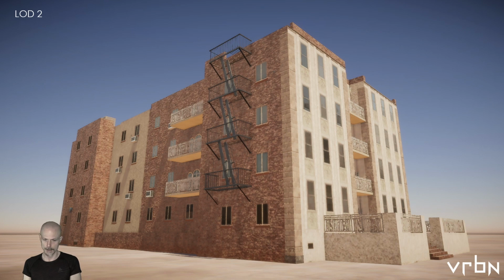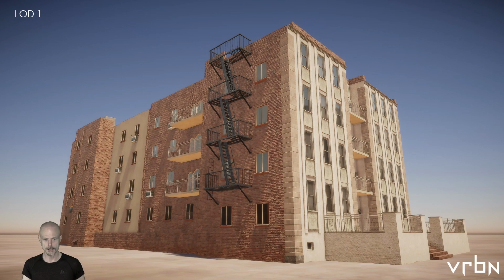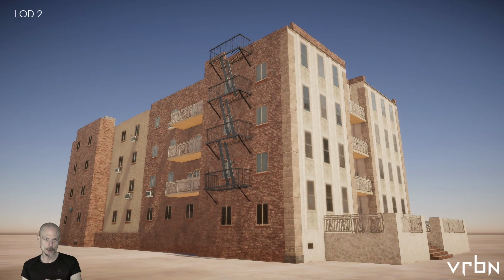And then another aspect I mentioned also before is the so-called draw call optimization for game engines. That's reducing the number of materials. So if a building like this has, let's say, 20 or 30 or 40 different materials, this means 20, 30, 40 or 50 draw calls. Now, switching from LOD 1 to LOD 2, in this case, here we have baked everything down fully PBR, but into one draw call. This is a huge optimization step.